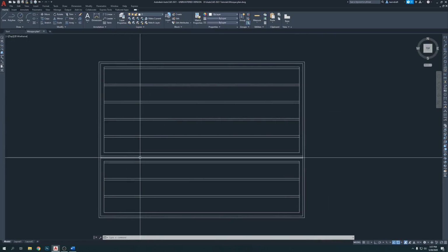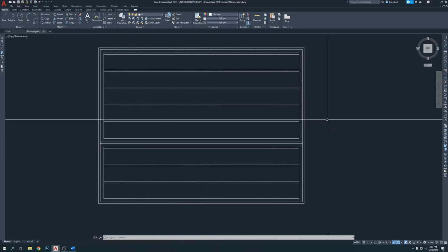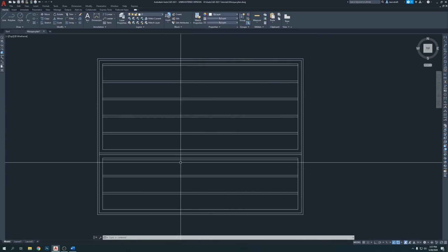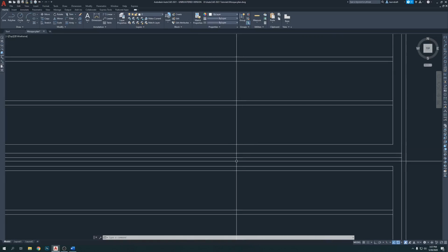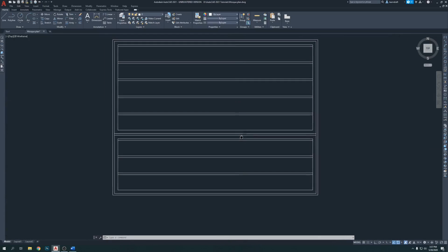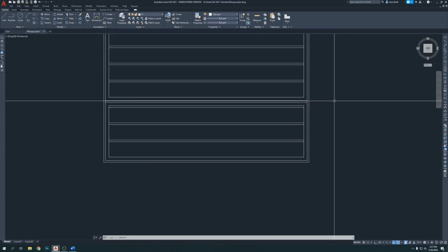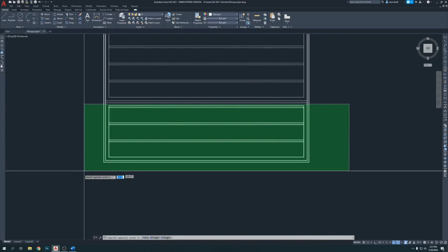Another thing, this wall we cannot make 6 inch, we need to make it bigger. Why bigger? Because a lot of load is going to be there, and the column is going to be bigger, and if we keep it 6 inches, then the column will come out this way or that way. So we need to extend this way instead, towards the main mosque.